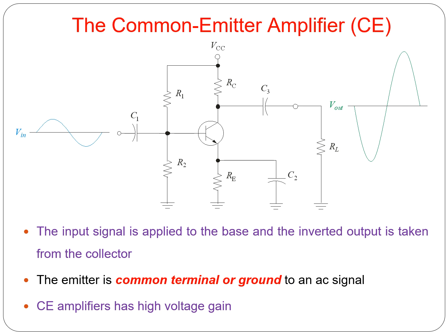Common emitter amplifier, foundation of gain. So as we kick off part two of our BJT amplifier series, we return to a familiar and essential configuration, the common emitter amplifier. This is where everything we learned in part one, from biasing to Q point setting, comes into play. In the common emitter amplifier, the input signal is applied to the base and the output is taken from the collector. And the emitter, you ask?